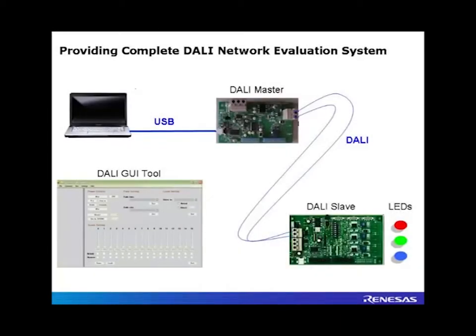So once the board is programmed with the DALI code, we can connect the system as follows. We connect the DALI master demo, which is called the lighting communications demo, with the USB cable to the PC, and connect the board we've just programmed as a DALI slave via simply 2 wires to the DALI connector of the DALI master board. You can connect more DALI slaves, even custom ones if you like, to the same connection just to have the DALI bus, the common bus.